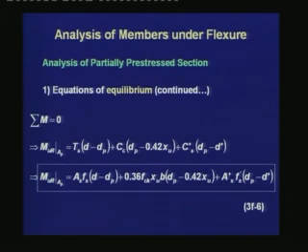The second equilibrium equation is for the moment. Now here we are writing the moment with respect to the axis passing through the CGS. The moment at ultimate is represented as MUR, or ultimate moment of resistance, that is equal to the summation of the individual forces times the lever arm.